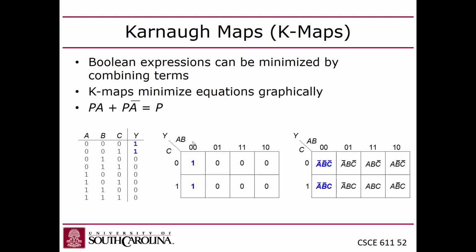It's like, I don't get it. Why does that work? Well, if you put it on a Karnaugh map, you can figure it out. The reason why consensus works is because you start out with these three implicates, but one of them ends up becoming common amongst the other 2, so you can take it out. So that's just another example of the use of a Karnaugh map.